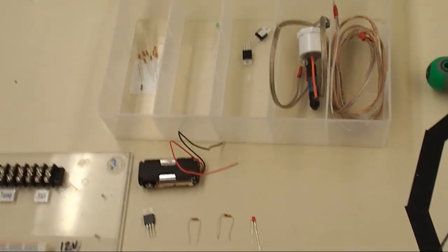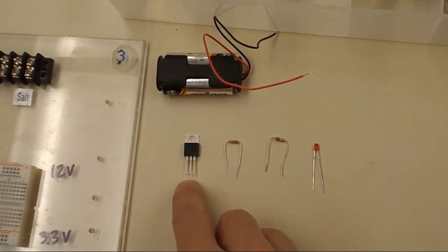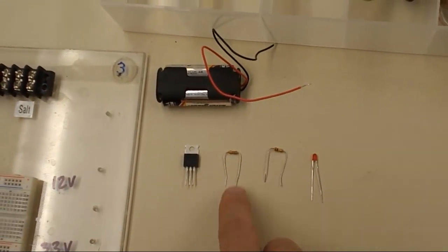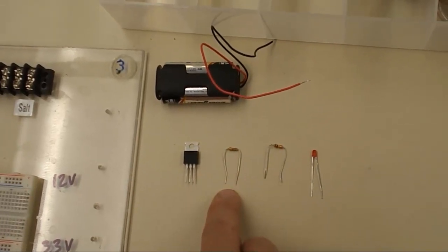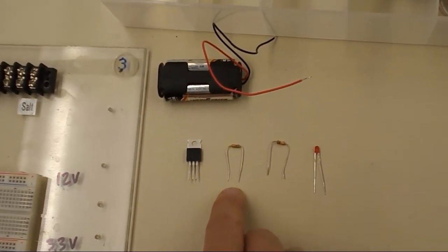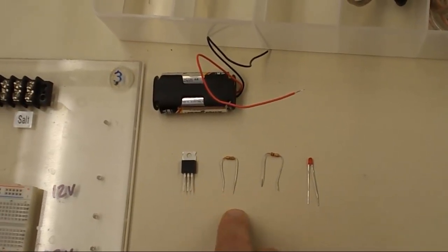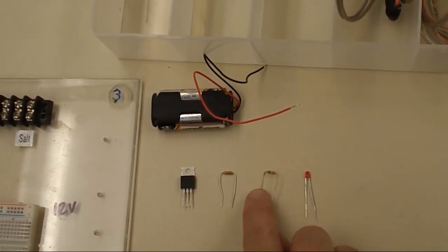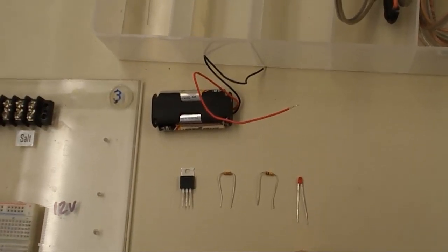So, pulling out the supplies for just the first circuit, we've got a transistor. It's called a TIP31A. I'll show you a little bit more about that in a second. I chose a resistor. You'll have to choose specifically. If you choose this one, it may or may not be right. So I suggest that you do that calculation before you choose your base resistor. This is the 100,000 ohm resistor that we'll use for the pull-down resistor, and then I chose the red LED for our first circuit.